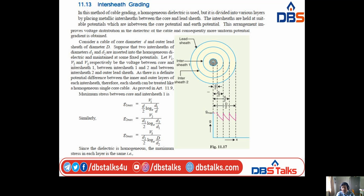In capacitance grading, composite dielectric is used. Coming to Inter-Sheath grading, a homogeneous dielectric is utilized, but it is divided into various layers by placing metallic intersheaths between the core and lead sheath. Intersheaths are held at suitable potentials which are in between the core potential and earth potential.